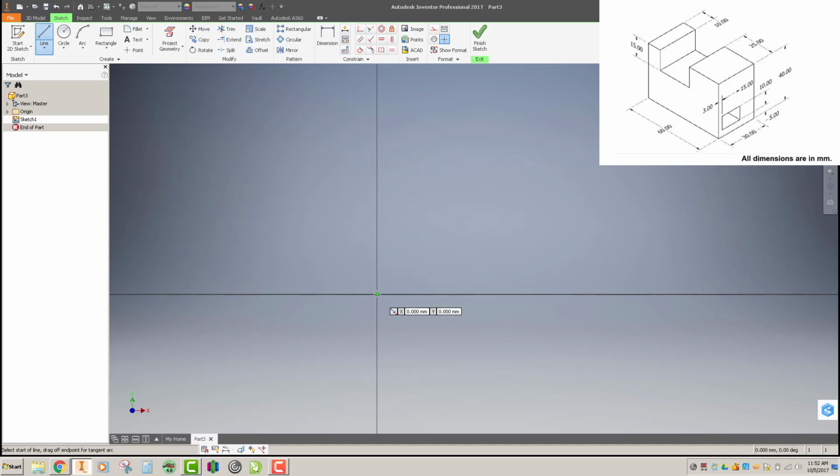Always start my sketch locked to the origin, and I will draw a vertical line up and then a perpendicular line, and all along I'm applying some geometric constraints that I know I want so that it can quicken my drawing process here. So we'll get that rough front view sketched out here. And then we will come back in and put some dimensions on.